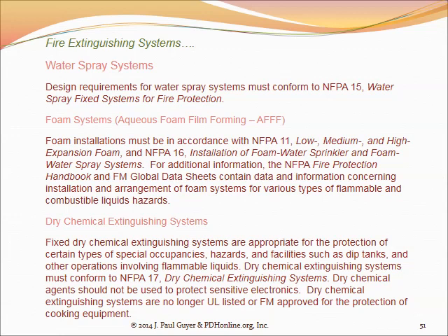Dry chemical extinguishing systems. Now these are ones that in ordinary day-to-day building design you may well encounter, because these are the ones you would use typically in a kitchen. And again, the challenge here is that the fires that pop up in kitchens are grease fires, and the grease floats on top of the water and you can't put the fire out. The place where these fires are the biggest risk is at the cooking surfaces of stoves and things like that, and in the fume hoods that are exhausting the fumes from the cooking surface.